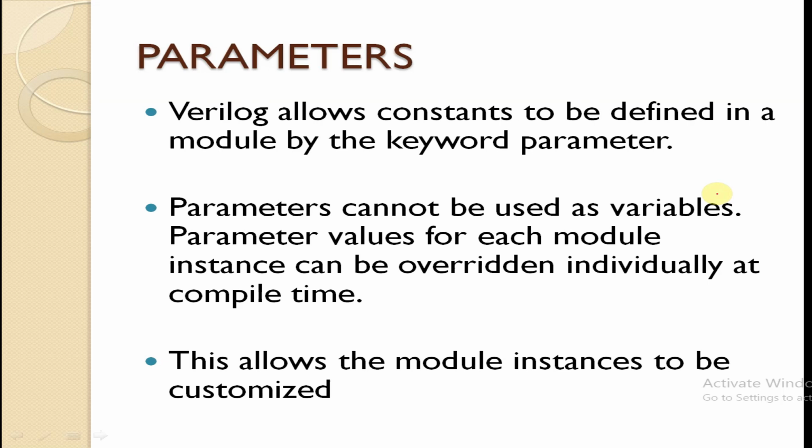Special characters, system tasks, and compiler directives. So coming to parameters, Verilog allows constants to be defined in a module by the keyword parameter. So there is a term called parameter which is a keyword in Verilog. These parameters are used to define constants.